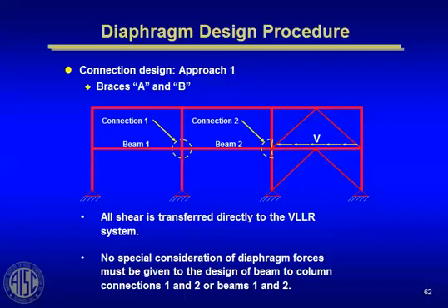If you look at this in elevation, there's your brace frame over there. You're dragging all that diaphragm shear only over the width of the lateral load resisting system, and that shear is small enough where the diaphragm can resist it without a shear failure. This is typical of what you would find in a wind load condition. Diaphragm shears aren't very big. This is not a problem. Matter of fact, it's so little of a problem we don't even pay attention to it.